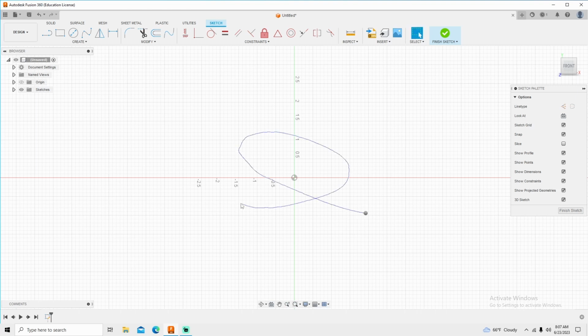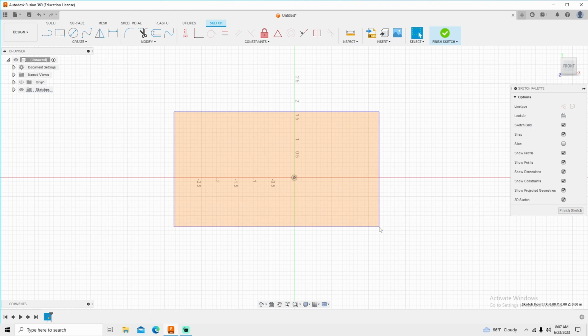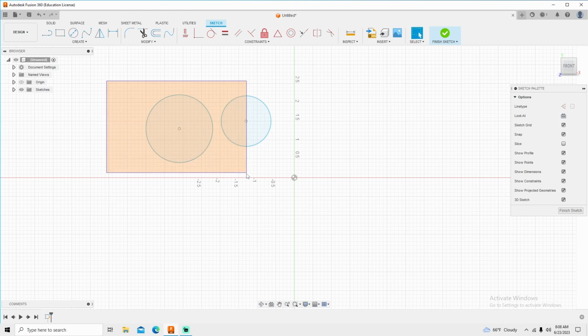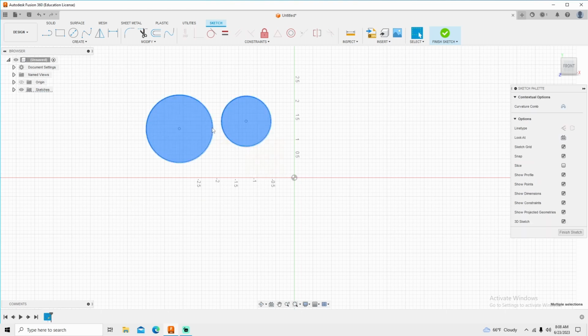My right click draws this funny little line that actually highlights stuff. Then my left and right with this is select all. If you click and hold left, drag up into the left is select all. If you click, drag right and down, that is partially select, and it only selects what is completely within that square. I'll actually show you how that works. So let's say I've got two circles on here and I click and come this way. You'll see that it only selects the one that's completely encapsulated by the rectangle. But if I click up and get even a little bit of it, it's selecting everything, even if I just grab a corner of it.